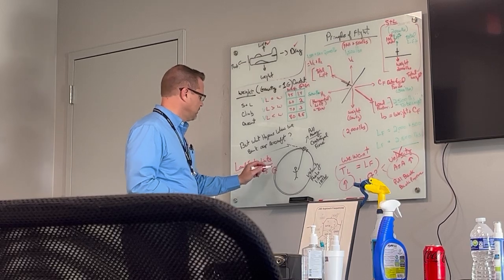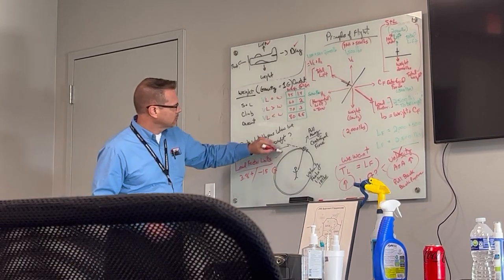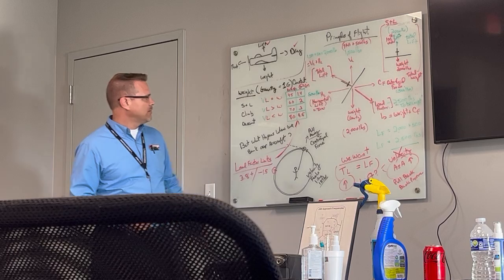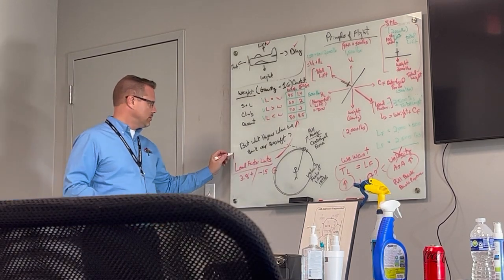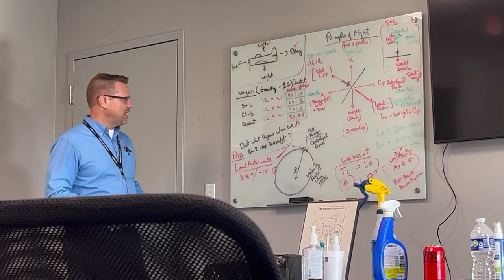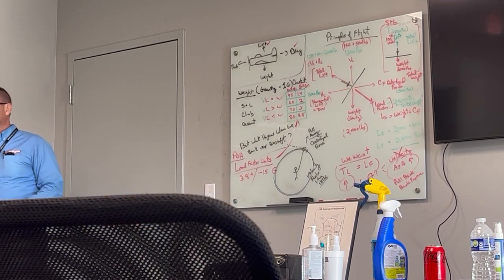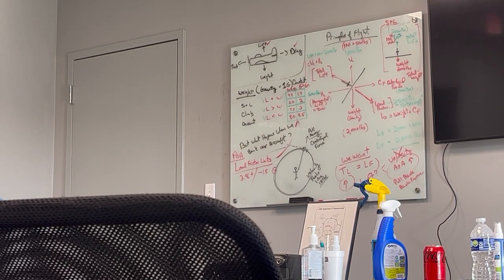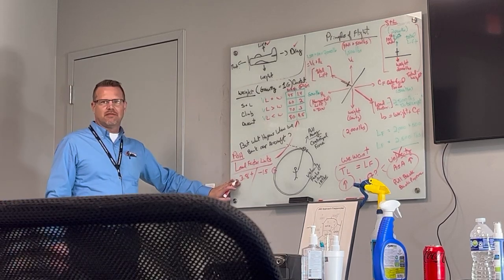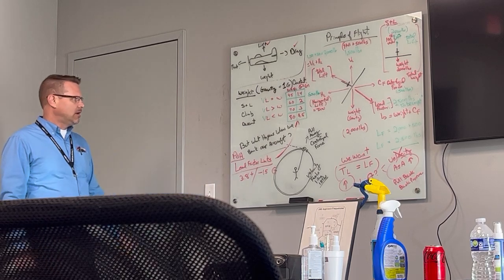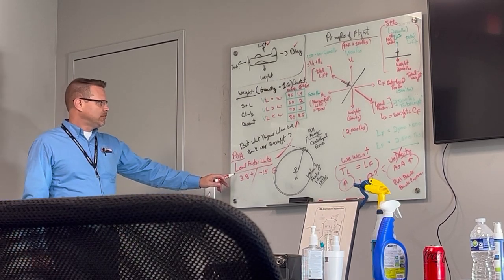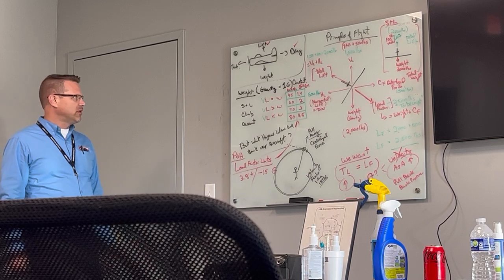That's Gs, right? So why do we care about this? Because per our POH, Pilot Operating Handbook, our aircraft has certain limits. And again, if I'm writing the wrong limits, please write the limits down for your plane. Cessna and Archer may be a little different. They should, typically, this is the normal range for a normal category, general aviation aircraft. So, positive 3.8, negative 1.5 Gs.